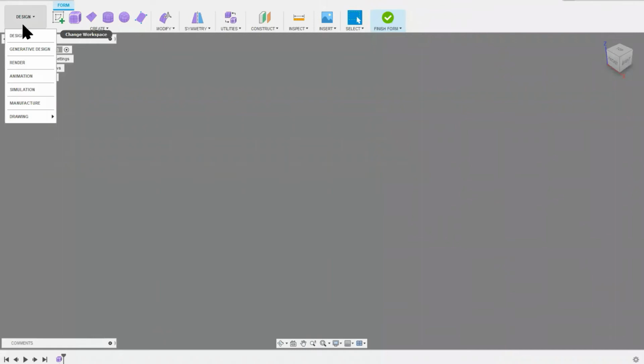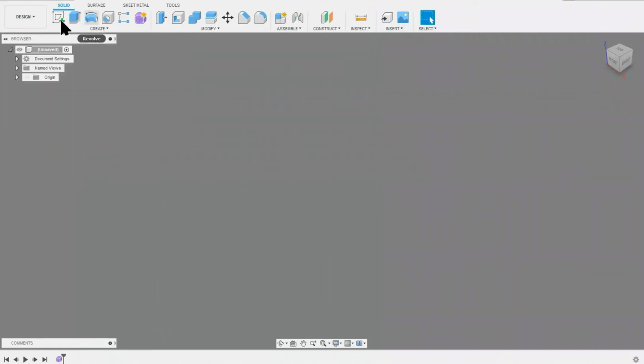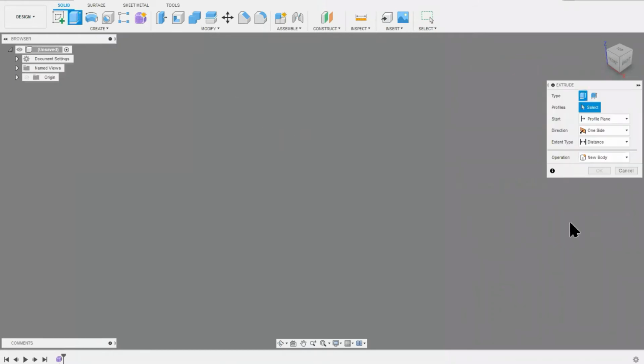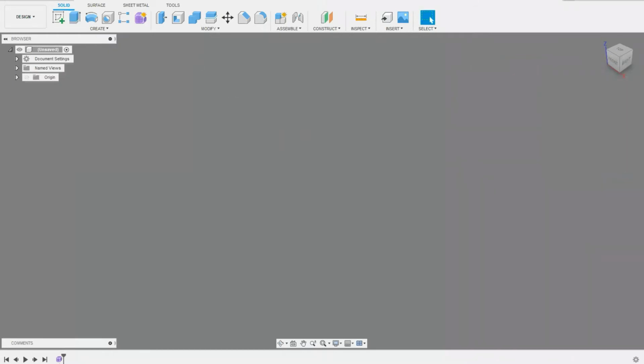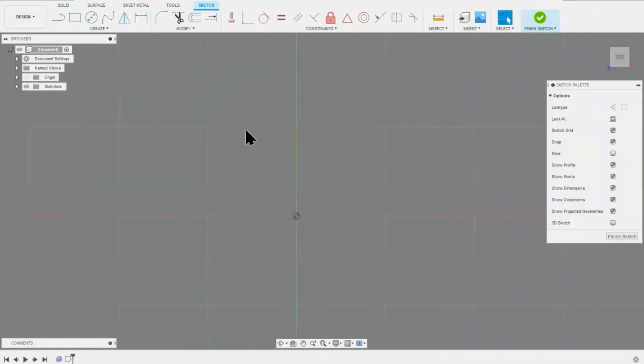Okay, so what I'd like to do today is, first up, we're just going to talk about some surface modelling options. And just to give you a bit of a rundown, very quickly and briefly, in the solid side of Inventor, if we create a solid shape, we start off with a sketch maybe, and I can draw a shape here on my screen with my line tool. So we could draw a shape and simply close that shape.